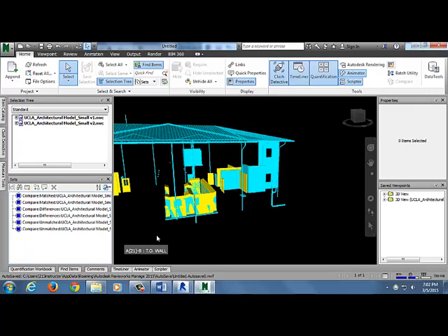So if I want to hide my reds, that's the matched, right? Or if I just want to keep the reds, I have to hide the differences. So matched is white, differences is red, right? And then the unmatched is blue and yellow. So if you wanted to hide everything else, you would click on the two differences, and then hide it. And then you can toggle back and forth between the two.